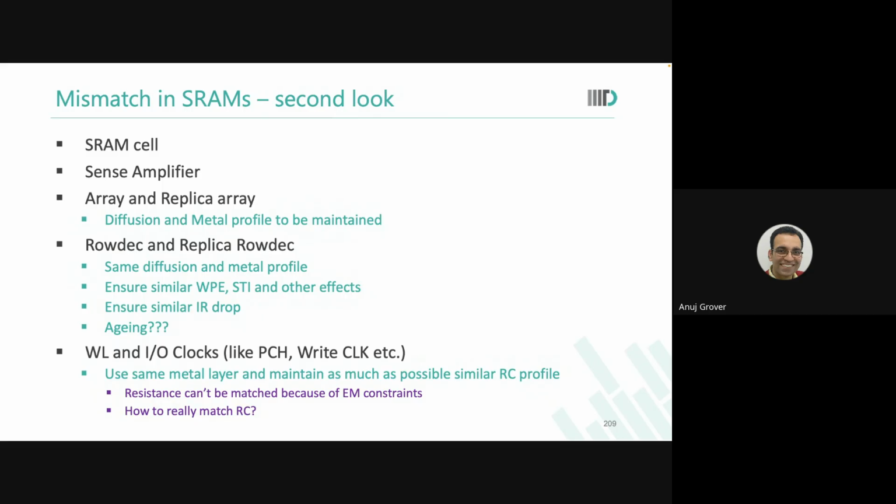I mean, if you look at a replica bit cell or replica word line, you will not be able to tell the difference. Unless you go into detail with the lens in your hand and say, okay, where are my VIA2s which are connecting the word line to the gate there? So you will say, oh, in this particular word line, VIA2s don't exist. So this is a replica word line.